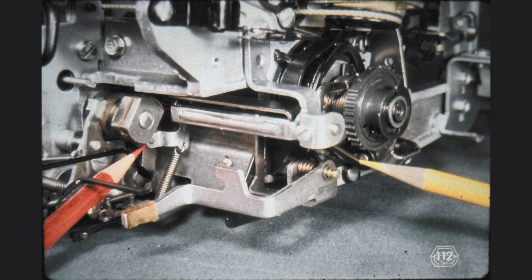Timing: when the machine is at rest, with the cycle shaft resting against the check pawl, the cam above the red pencil should be holding the cam follower so that there is a distance of 1 to 1.5 millimeters between the lug, indicated by the yellow pencil, and the teeth of the shift ratchet. Furthermore, the shift lock cam should hold this condition with its leading edge, so that only a small amount of turning of the filter shaft will prevent the operation of the shift clutch.